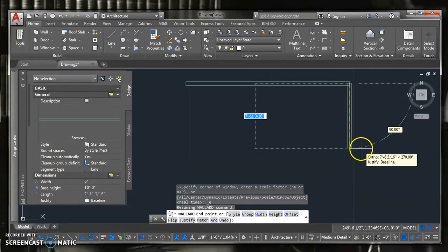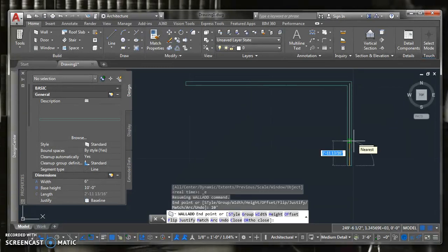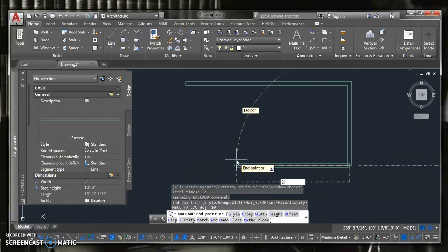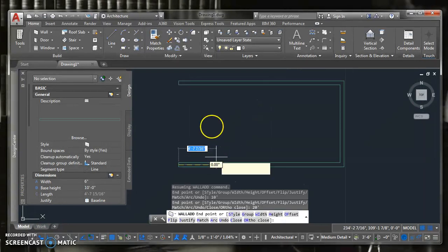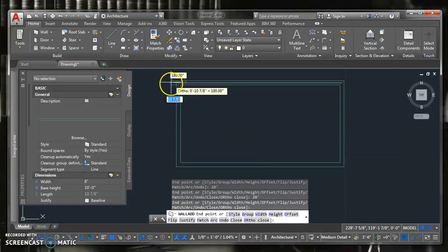Now that's just our first wall. If you notice, our wall is still trying to go in other directions. We might as well finish it in my mind. So if we went 20 feet over, we're going to go how far down? That's right, 10 feet. So I'm going to type 10, apostrophe, enter. Again, we're going to go back our 20, apostrophe, enter. And finally, back up. If you see that green box showing, that's what you call a snap point. That'll automatically connect to them. So you just move it up there and click.